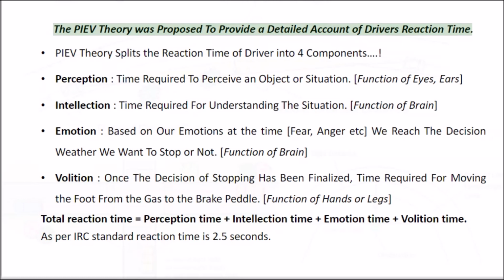The PIEV theory was proposed to provide a detailed account of drivers' reaction time. PIEV theory splits the reaction time of driver into 4 components. Perception: time required to perceive an object or situation, function of eyes and ears. Intellection: time required for understanding the situation, function of brain.